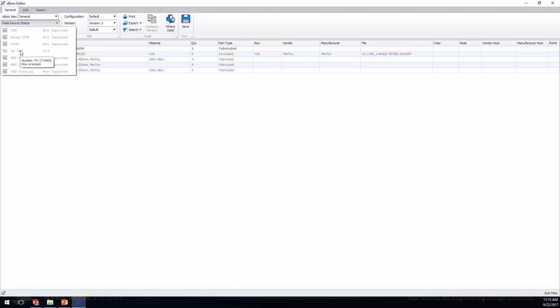Again, I'm just reading the structure directly from PDM, but then going into those configuration settings and honoring whatever you've chosen and how you want to organize those assemblies. I would get the same results if I'd used the CAD drawing assembly BOM or set up a data source for the assemblies BOM as well, just because those obviously obey that ordering as well. But again, that's why we've set that up.